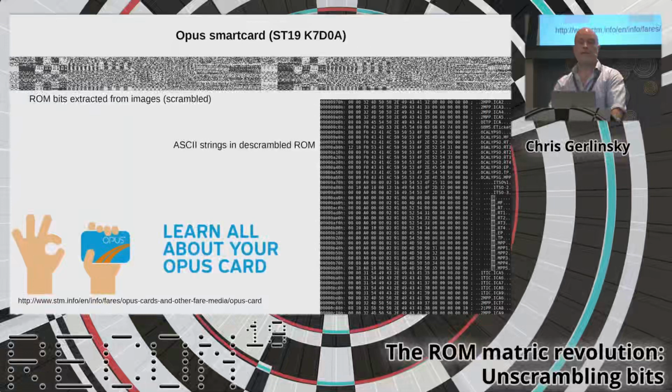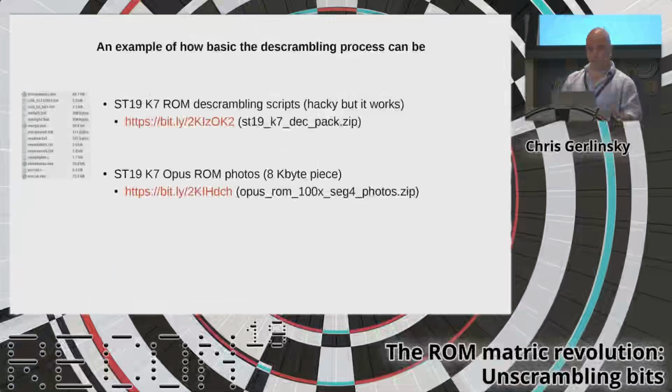So in this case, I was able to do the research into the ROM scrambling on a different platform, on a different product, and then I was basically able to rerun my series of scripts on the extracted data from this card and decrypt it no problem.